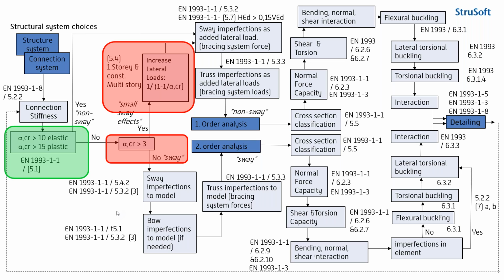How did you come to the connection initial stiffness being equal to the secant stiffness, or did I misunderstand? The initial stiffness is calculated based on the component stiffness, and maybe the utilization in the connection was so low that it does not need to be taken into account. So if the utilization is low, then the final stiffness and the initial stiffness are identical. But if the utilization becomes higher, they will deviate.